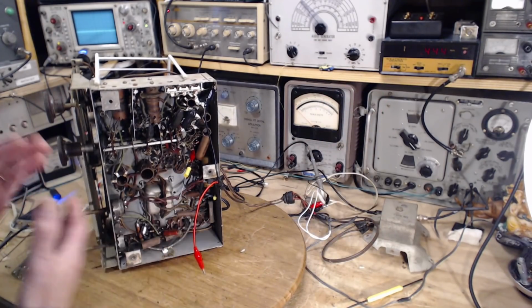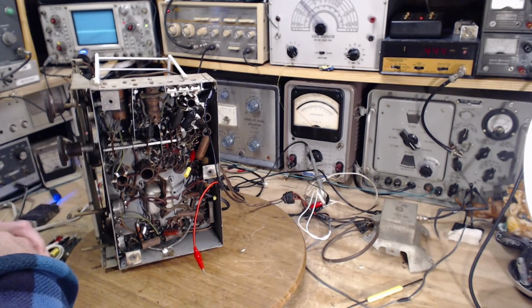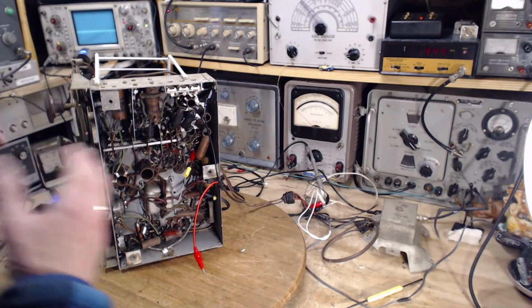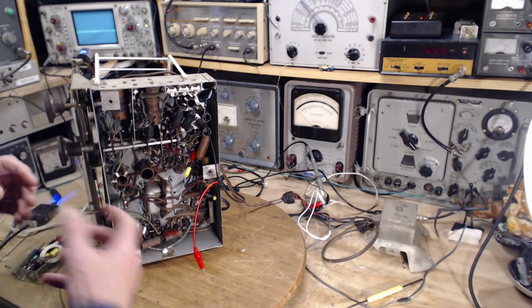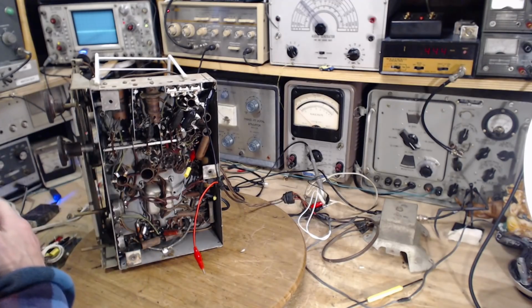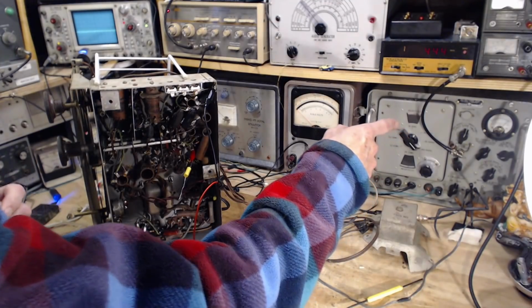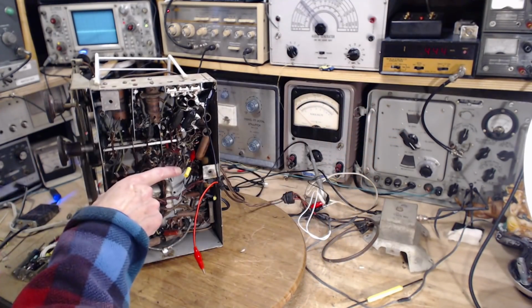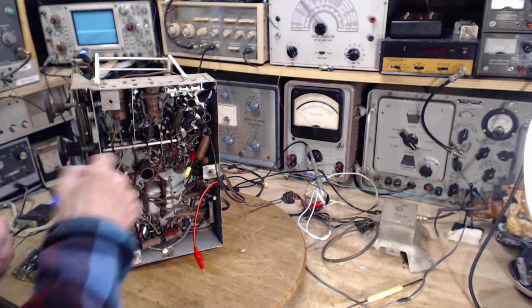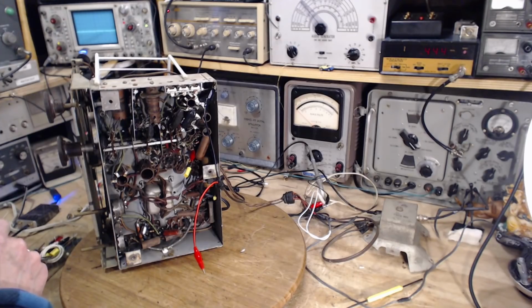So what I've decided to do is skip the whole front end of the radio, the RF part of the radio, and feed an IF signal right into the IF. Should amount to the same thing coming out of the speaker, unless there's something wrong in the front end that's causing the distortion that we're seeing. So to that end, I've got the signal generator ready to go just below 455. I've got a clip lead clipped onto the grid of the mixer tube, the signal grid of the mixer tube.